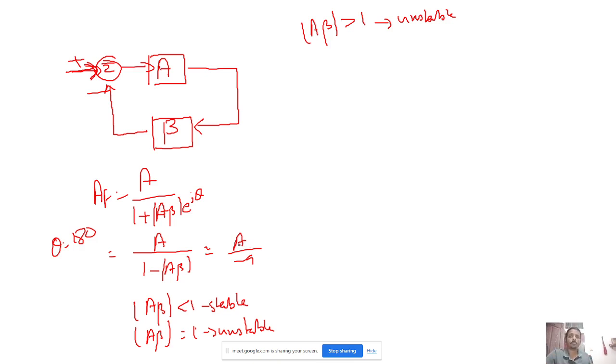So it actually should have been stable. Sir also mentioned as a statement that though it seems to be stable, actually it is unstable. For that we have to check, if for example an error signal comes in, how that will affect the output. Suppose there is some error signal here, an input, and a feedback signal input here. So the error will definitely be equal to Vi minus Vf.